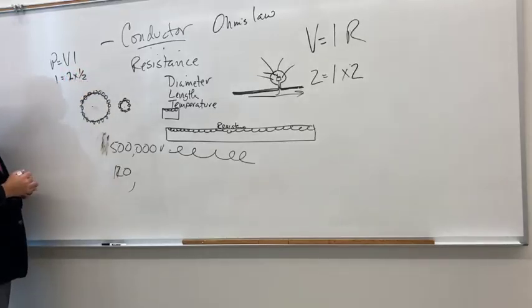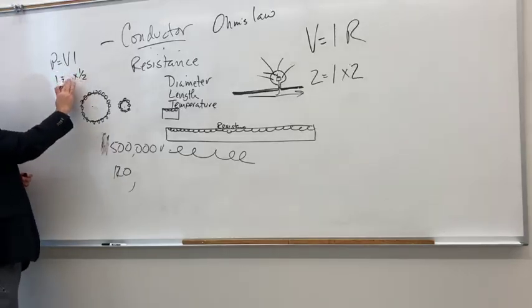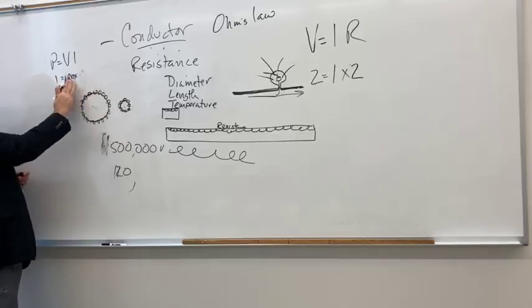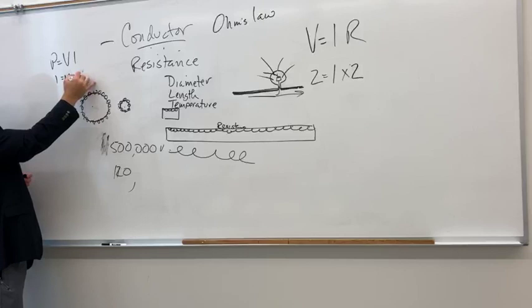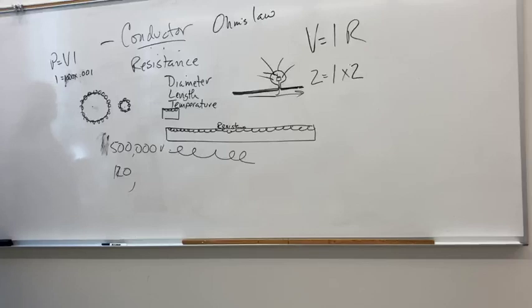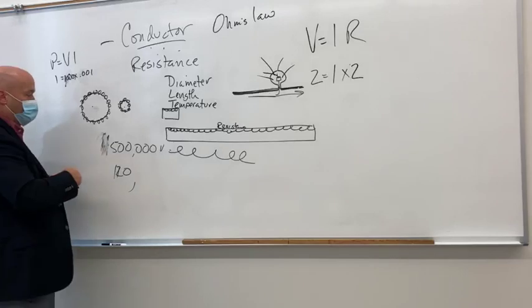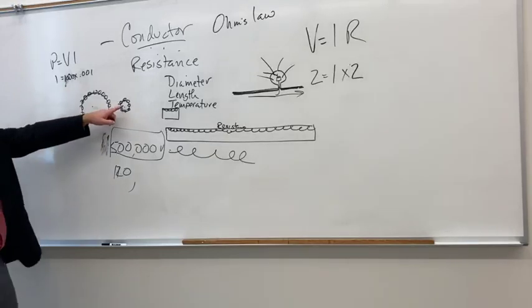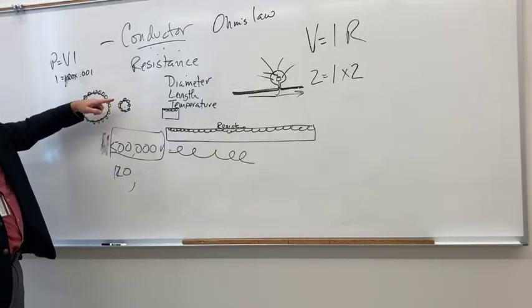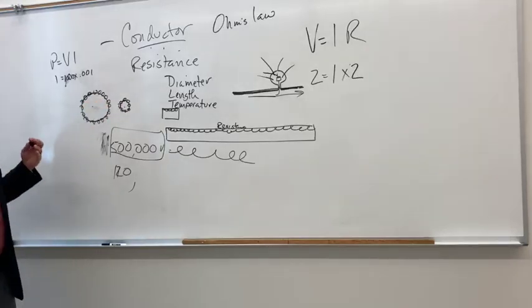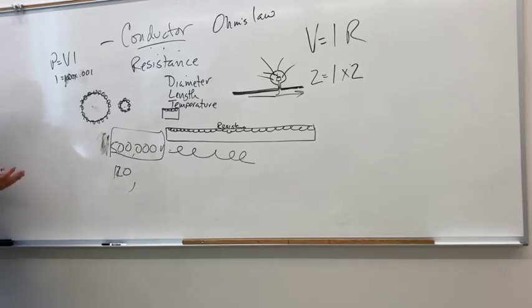Half it, right? So if we increase our voltage by a factor of 500 times, let's make it easy, let's say 1,000 times, then our amperage naturally is going to be 0.001, right? So we can trade off very high voltage for very low amperage. The reason that we have such high voltage coming from the power company is for that purpose. So we can use a much smaller wire with higher resistance to send the same electricity to your house.